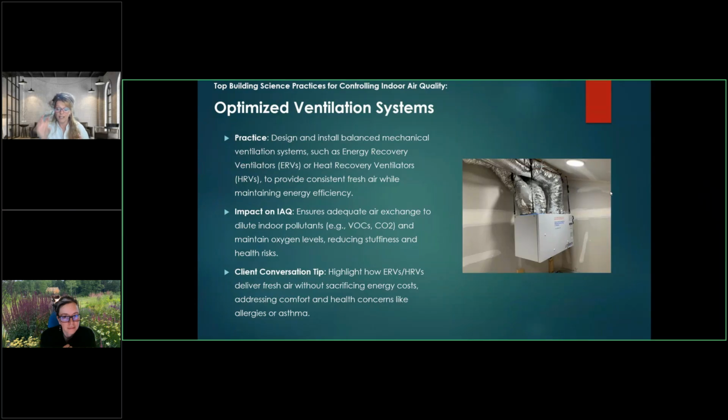If you want to keep them separate, a colleague of mine, David Treelevin, wrote an article in Green Building Advisor several years ago on how to integrate ERVs and DHUs into designs, and the pros and cons of the options. But ultimately, keeping them separate is always what you want to do. Just let the ERV provide the outdoor air, and let the dehumidifier dehumidify the house. But again, if you can't afford both, then going with the ventilating dehumidifier is probably the way to go.